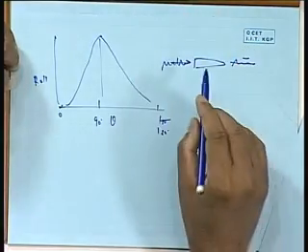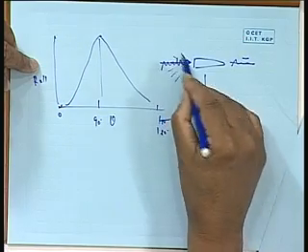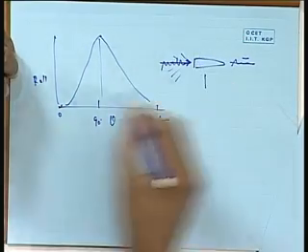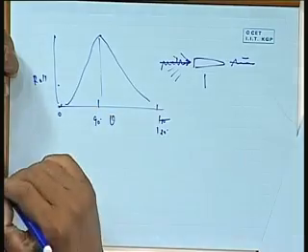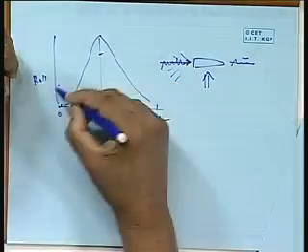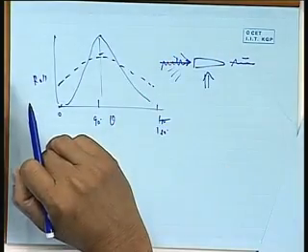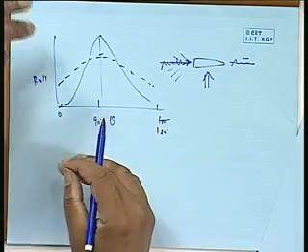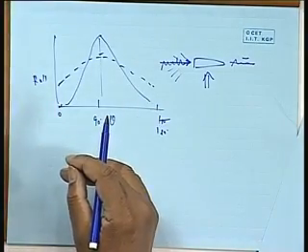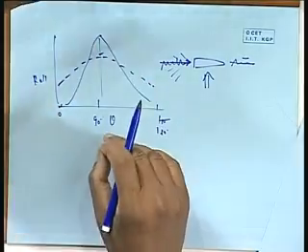But now if you assume that, look, although my dominant direction is this, my waves are actually spread over. If I take a short crested assumption, then although it is 0, there will be some roll here, and when it is 90 degree also, there will be a maximum but less than this, so the roll curve will look something like that if you take a short crested spectrum. What is this angle? This angle is normally defined as the dominant wave direction. In other words, in case 1, all the waves were in that direction only. In case 2, most of the waves are in that direction, but there are quite some waves also from other directions spread around that direction.